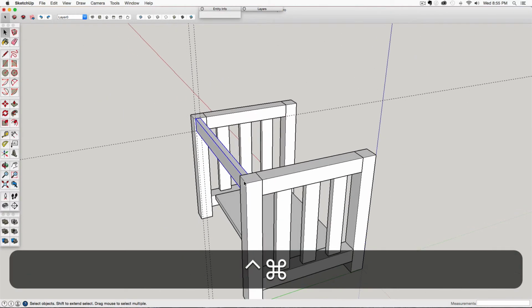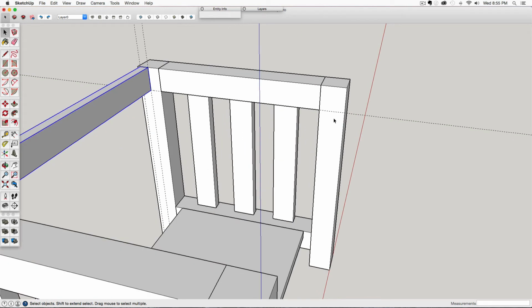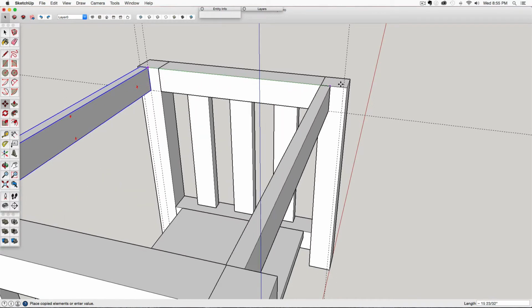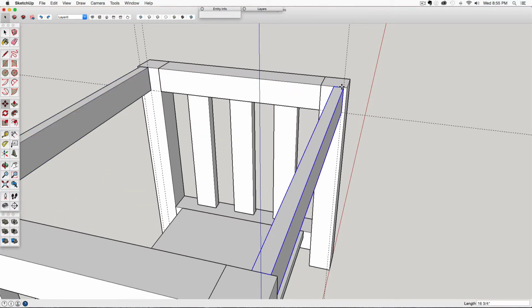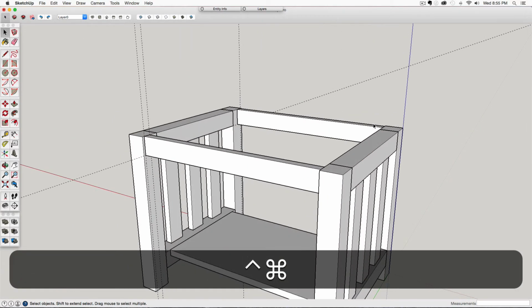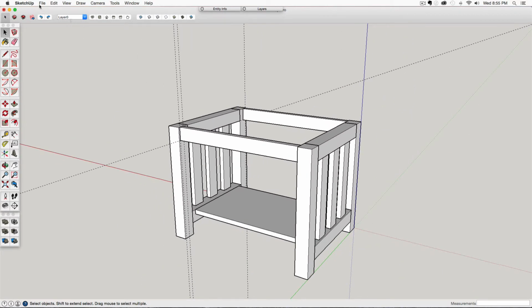Now here's a cool thing. Since we know that it's the same on the front and back, let's just come over here. Let's go in 0.25. Let's take this, let's move it with an M, and then Option or Alt click. Catch that corner, bring it over. I got a copy, put it in there. All right, let's delete our guides.